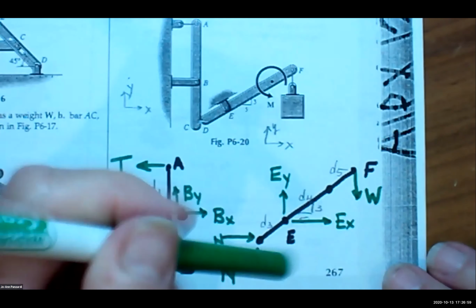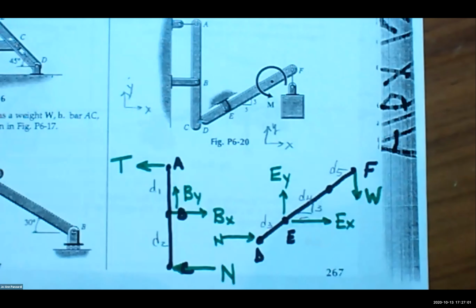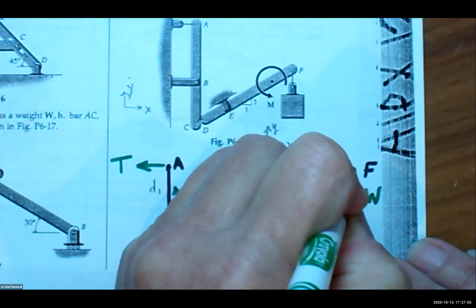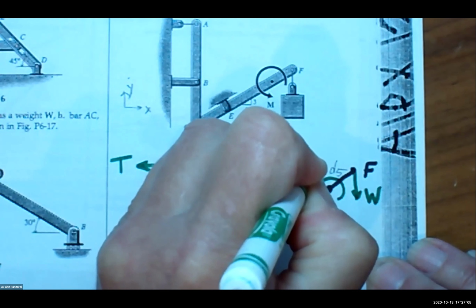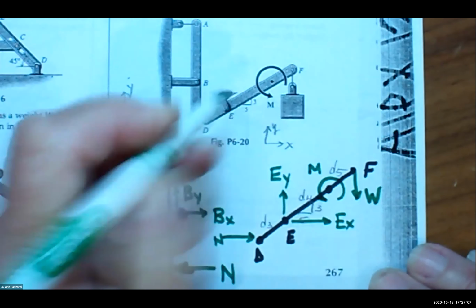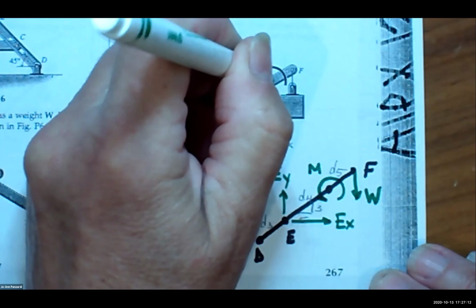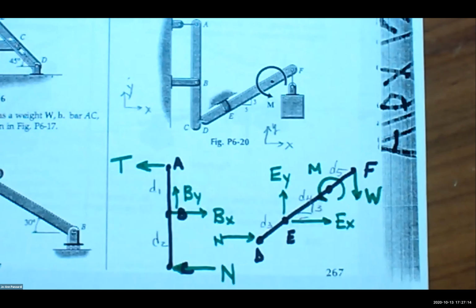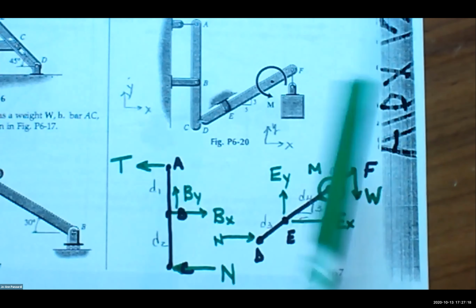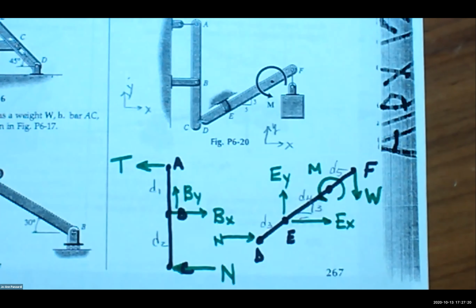Just like there's concentrated forces at times, this is a concentrated moment, and they're calling it M, and it's in the positive direction. It's being placed right at this dot. And Jack, knowing that this is a two-dimensional problem, what is that spin going around? The Z direction. So we have two free body diagrams here.